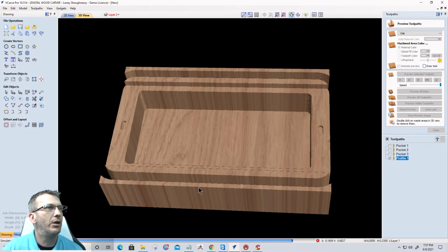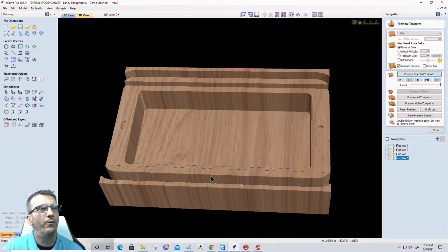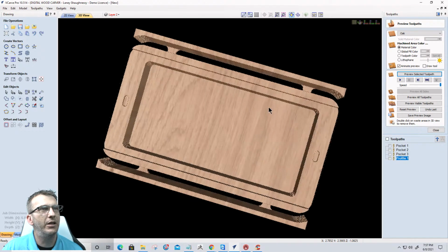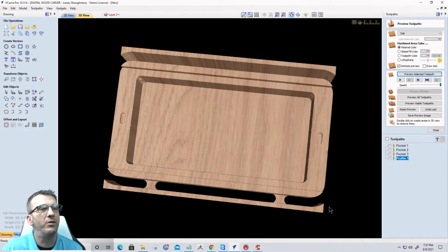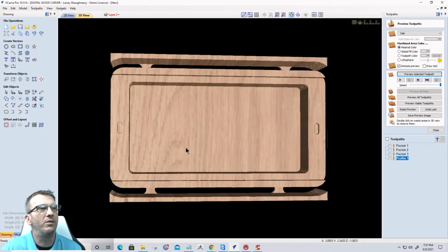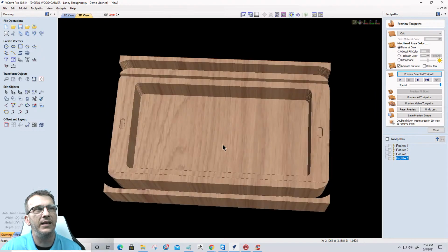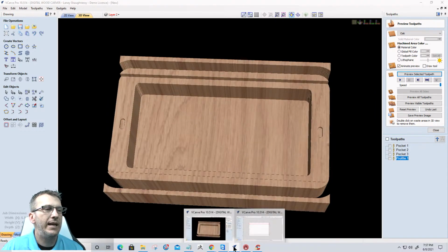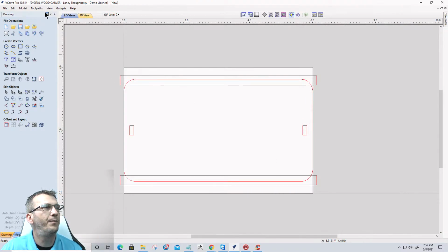Okay, and so on the cutout you can see how much room I have left. So when you're clamping, maybe use the two-sided tape method, or painter's tape and CA glue, or hot glue. If you're going to use mechanical clamps, give yourself a little bit of room, or make sure your clamps aren't overhanging, because we do not want to run into this, because the ends are going to get cut out and all that happy jazz. But this will be my box. All I'll have to do is cut those tabs, do a little finish sanding, and it's going to be good to go. And for the lid, let's now pop over to the lid here.